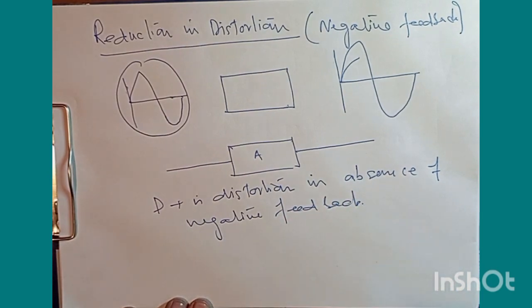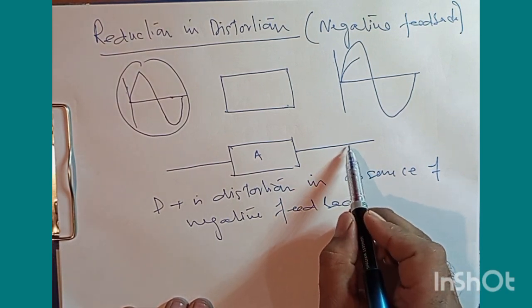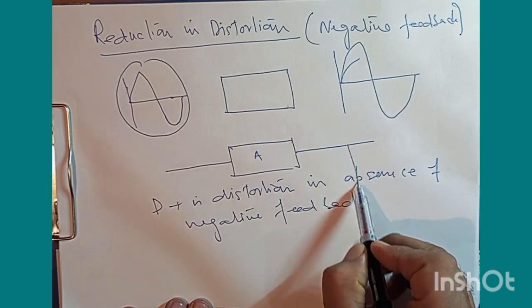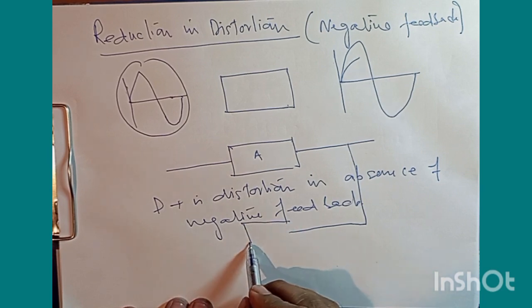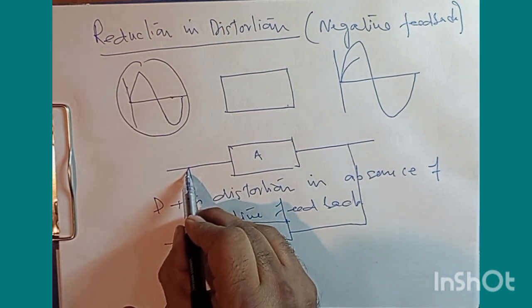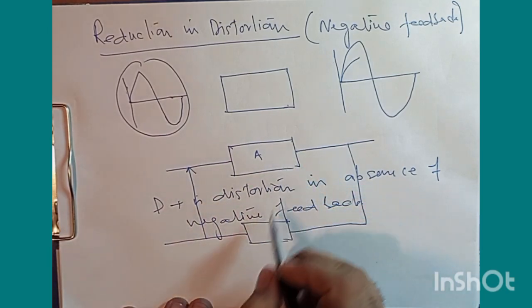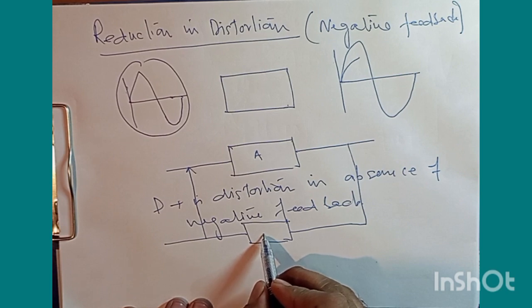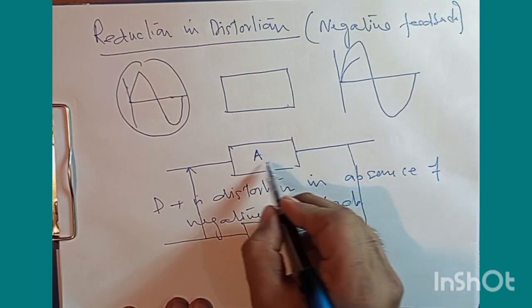Right? So the moment I make use of a feedback circuit, say I put it here like this, we have a feedback circuit here and we have an output here, and this output will be subjected back to the input signal of this amplifier. Let me assume that the feedback circuit has a feedback ratio beta, and A is the gain of the amplifier.